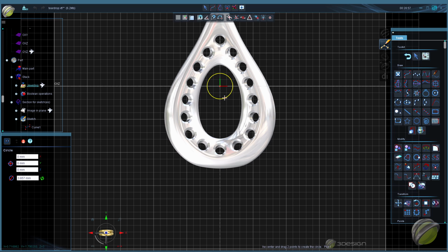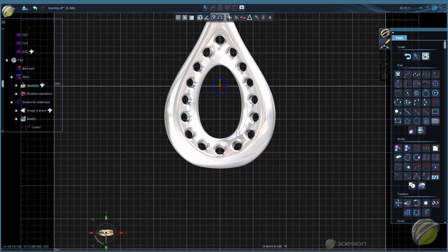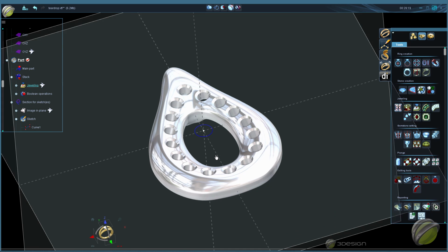So link that to the center, edit it so that we can make it, let's see, we've got 2 millimeters, we've got 0.6, about 2.25. There we go. Parametric, we can always adjust as needed, but I think my math's right there. We'll do 2.25. Exit your sketch.